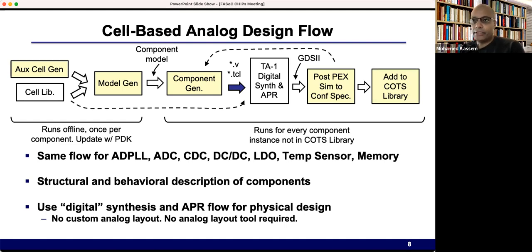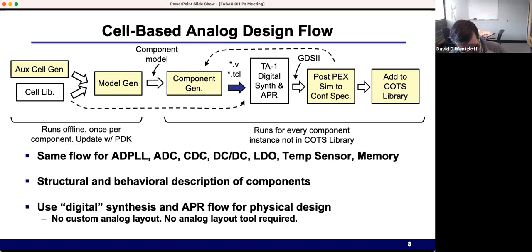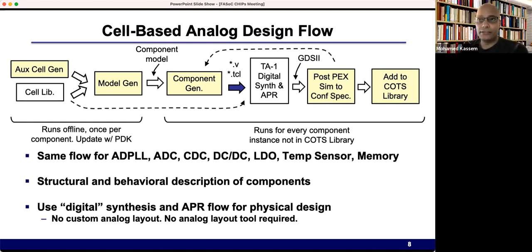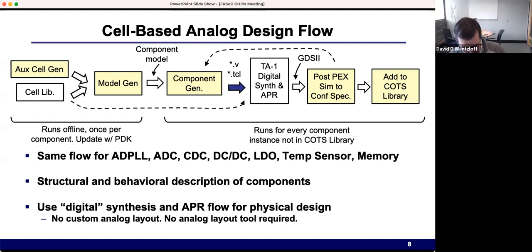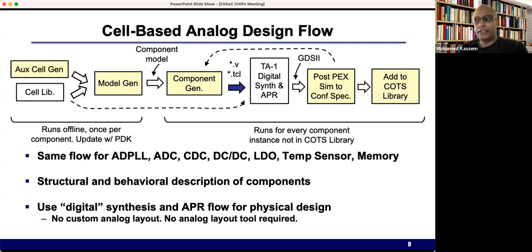This is just a simulation aspect. The Spice netlist can have whatever you would have, whether it's extracted or not, right? Yeah. But it's not selective, but it helped us a lot in getting rid of simulating the digital in the digital world, right? Yeah. And it's higher performance. And also we made some modifications to ngSpice to dump the same formats, so you can open the digital and analog waveforms together in the same viewer.